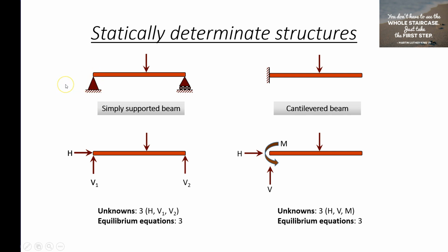Fine. So as I have said, if a displacement is restrained, there will be a reaction, right? And we have said a hinged support doesn't allow horizontal or vertical displacement. So along the horizontal direction there will be a horizontal reactive force, and along the vertical direction there will be a vertical reactive force. So the horizontal reaction is called H here, and the vertical reaction is represented by V1 here. Fine. And coming to the other end, we have a support called a roller support here.